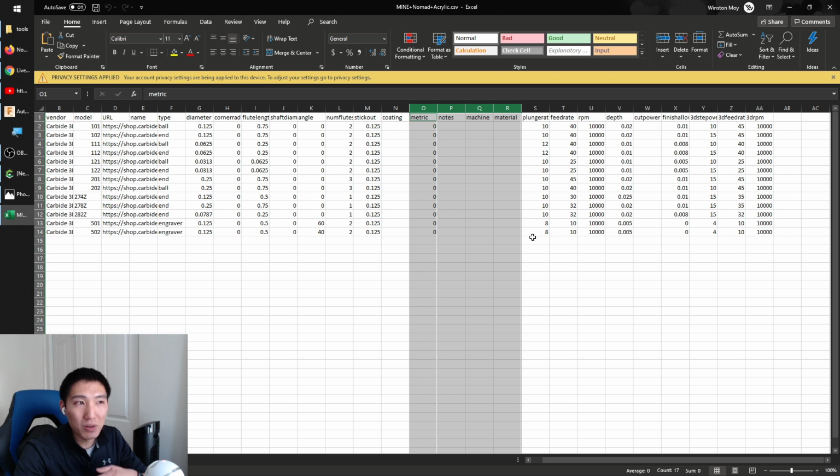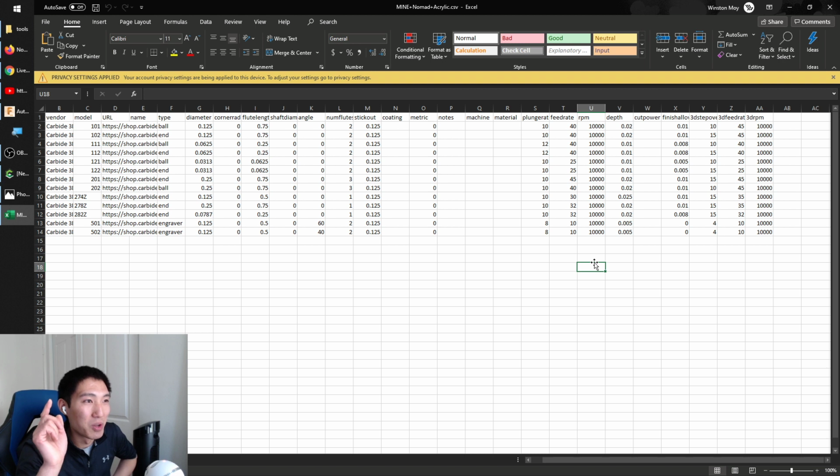If you cut deeper and slower, there's a different trade-off, but instead of only wearing away the very tip of the end mill, you're spreading out that cutting across more of the flutes. It's sort of a trade-off depending on what you're cutting and how you're cutting and what your priorities are. Rubbing is not allowed. You want to make sure that as the end mill is slicing through the material, it's actually shaving off pieces and not just creating dust, because that just means friction, that means heat, and that will decrease your tool life.